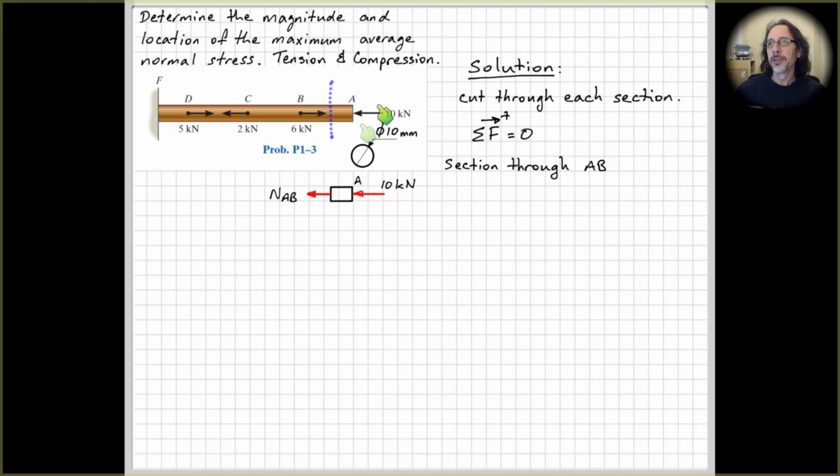This load that we have out on the end here is transmitted through the body of the structural component, and the internal action that we have here is what this left-hand side of the component does to the right-hand side. Now you can see here that I've put this acting to the left when it's quite obvious just by looking at the problem that it's actually going to be to the right for equilibrium.